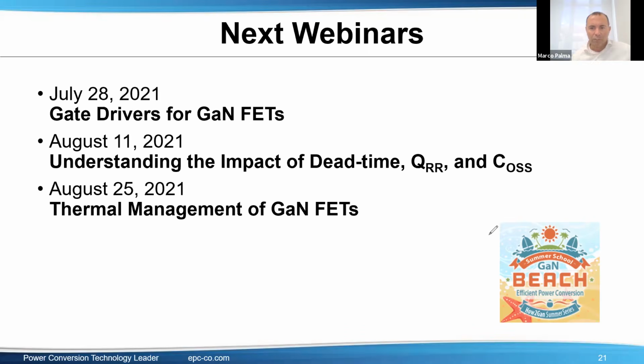Okay. Has GaN FET already been used a lot for PFC circuits? Oh, you're asking because here I'm doing a lot of DC-DC converter, and I'm also doing a lot of motor inverter, a little bit less than on PFC. Usually what is happening in a PFC is that GaN FET from EPC have so far the limitation on the maximum VDS voltage. We do low and medium voltage devices. On a PFC, usually you use a 650 volt device, which we don't have.